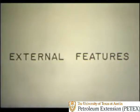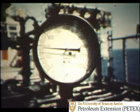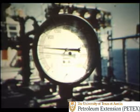Now that we've learned what is inside production separators, let's examine the external features. The first external feature we shall look at is the pressure gauge. The purpose of this instrument is for the operator to check the operation of his equipment and to aid in the setting of back pressure controls.